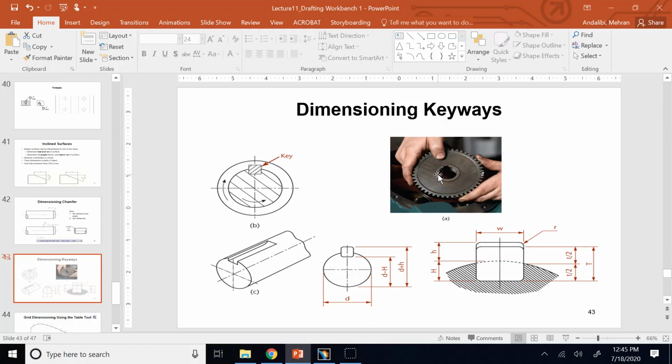And when the temperature goes away and they go back to their normal size, the shaft gets bigger, the hole gets smaller. Now those two parts are basically pressed against each other internally and they won't get separated, so they can rotate together. That's one way.